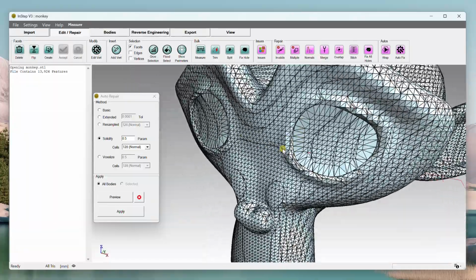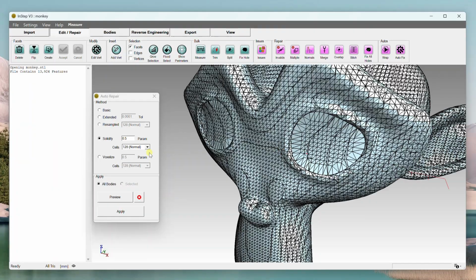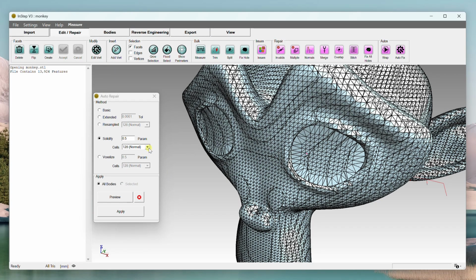It's a useful option in some cases, but I wouldn't rely on it too heavily. The main point is to start with a rough model and slowly work your way up. If you picked 512 right away, each of these is a step of 2 to the power of 3, so 8 times longer. So if, let's say this took 4 minutes, this would be over half an hour. And then this would be several hours to compute that. So keep that in mind.